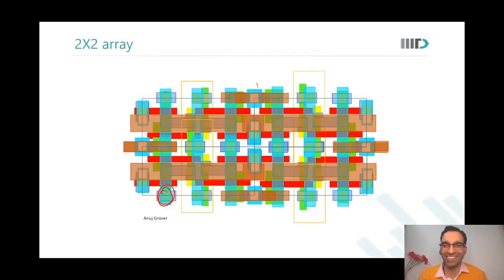Okay, sir. Understood. So whenever a new process node is defined, let us say I want to define the 3 nanometer process node now, the yield is actually ramped up on SRAMs. SRAM yield is determined, measured and tracked to see how the process has evolved, because SRAMs push the technology limits there. Yes, sir. Understood.